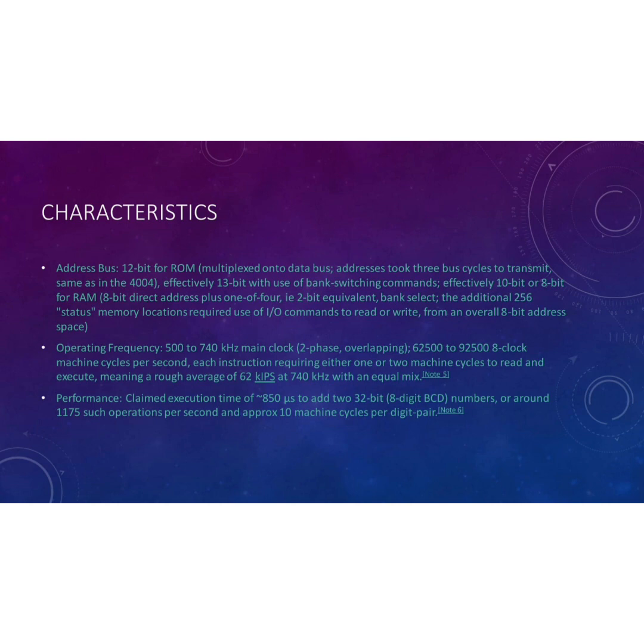And characteristics of Intel 4040. It has address bus, operating frequency and performance. First, address bus. It has 12 bits of ROM and 13 bits with bank switching commands and 1024 8-bit of RAM, and it has command to read or write from overall 8 bit address space.